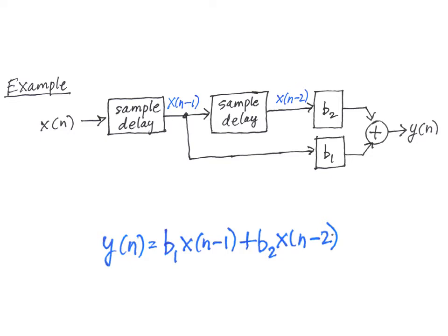And all of this may be related back to analog signals if what we started out with was an analog signal that was sampled to give us x[n]. Now we can do a particular type of filtering, and then convert back to the analog domain by reconstructive filtering of the samples, and essentially duplicate or even perform types of filtering operations that are impossible in the continuous time domain. So this is a very powerful technique.